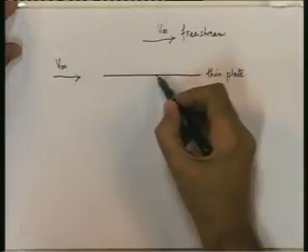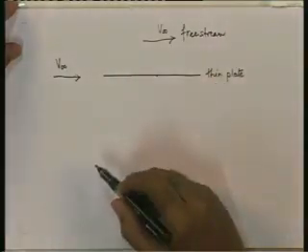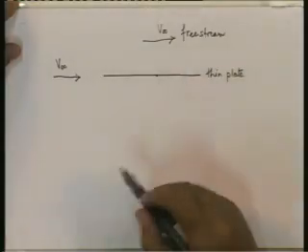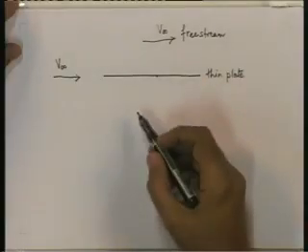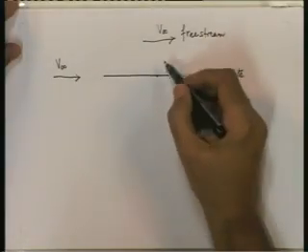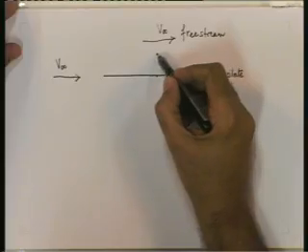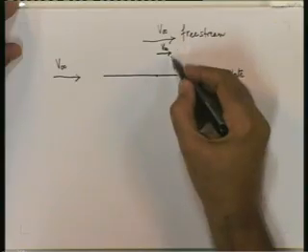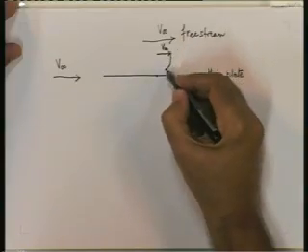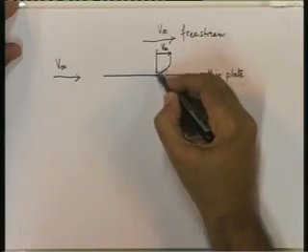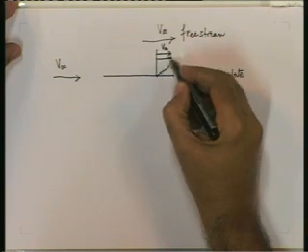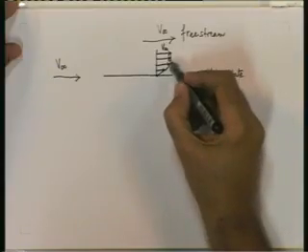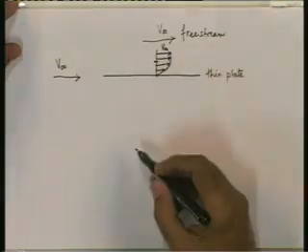However, the fluid at the surface of the plate will become stagnant because of the presence of the plate. The fluid will stick to it, and hence you will have a situation where you will have a V infinity away from the surface. The velocity will go down to 0 at the surface. And you will notice that the surface effect is felt only up to a certain distance.